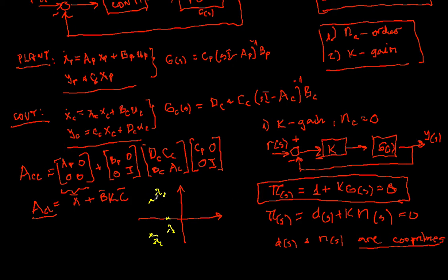This is for the fixed gain. These eigenvalues will move, for example, will migrate, and they can cross the imaginary axis. So there is some instance of the gain where these eigenvalues are crossing the axis, and these eigenvalues become from negative positive, which means the system becomes unstable.